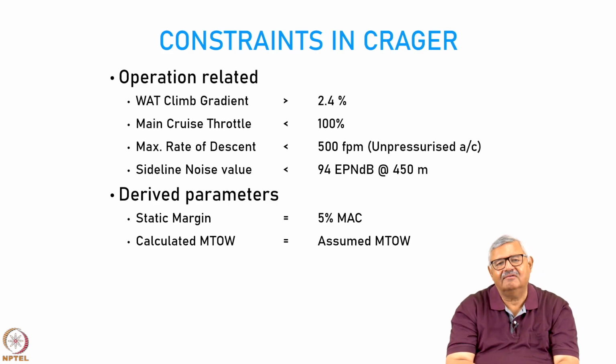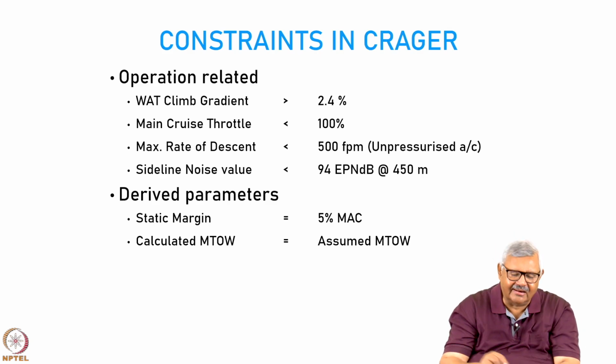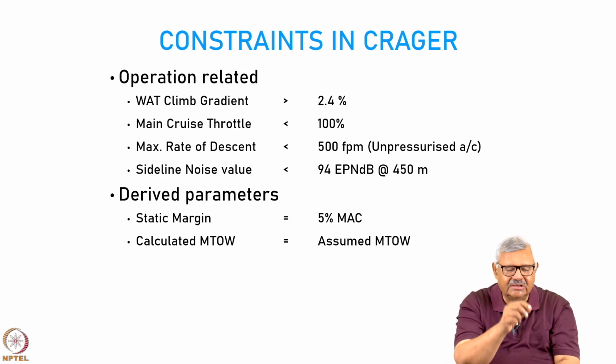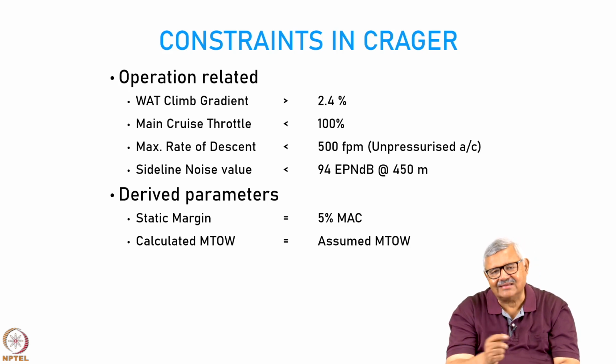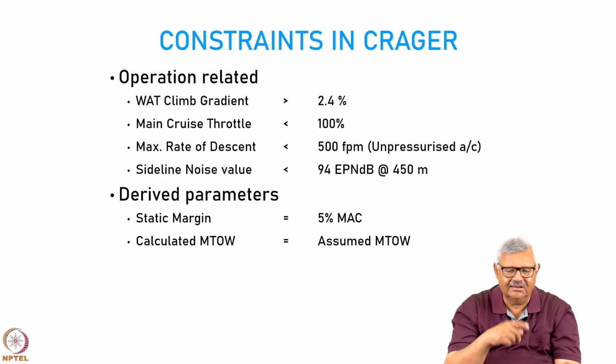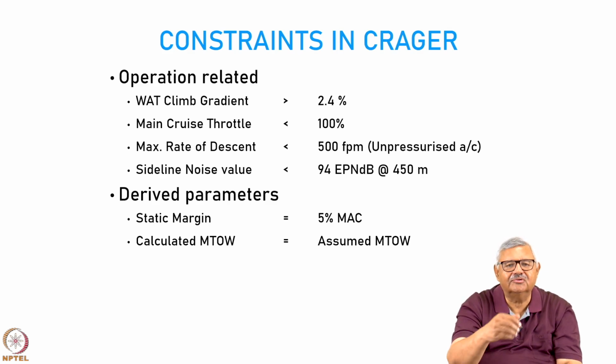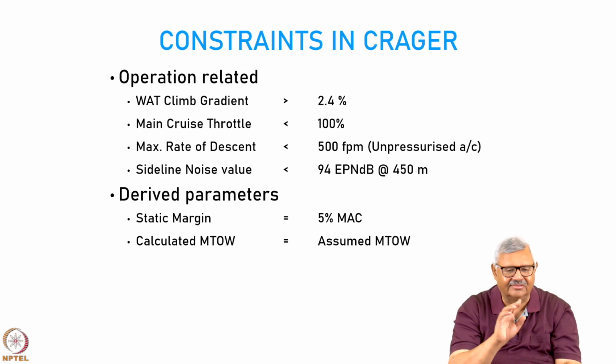In the normal aircraft design code, you do a lot of iterations. You change the parameters and you iterate till the maximum takeoff weight converges to a value. Now, that takes time, and it can lead to complications, especially if you have multiple loops. So, what we have done in this is, we have brought in a new interesting concept. We leave it to the optimizer to help us crack this problem.